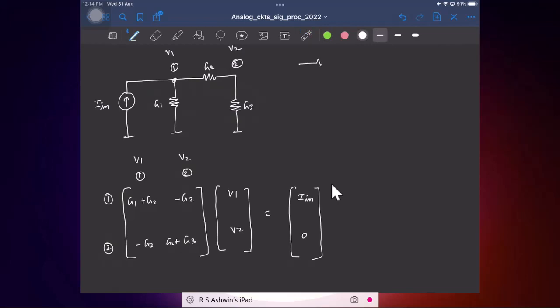Let us say you have some conductance in some circuit between nodes, say I'll label them L and P, and the conductance value is Gx. So you'll form the G matrix, and let's say this is the Lth row, this is the Pth row, and these are L and P. What will be the entries for Gx? On L comma L I'll have Gx, and on L comma P minus Gx. Here it's minus Gx and Gx, right?